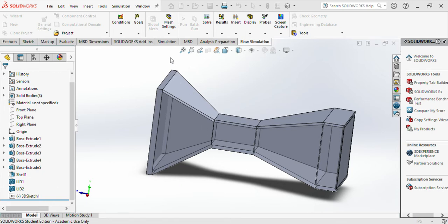We'll also be using internal and heat conduction in solids. If you are using a fan in your wind tunnel simulation, then I would recommend you also add rotation to it and apply it on the propellers of the fan. For our gases, we'll be going with air.